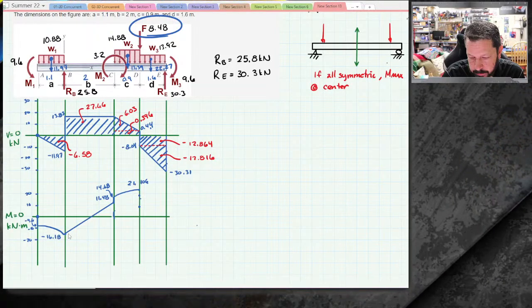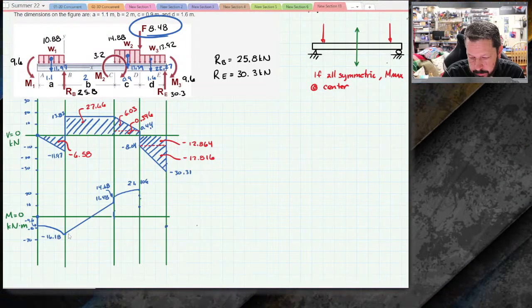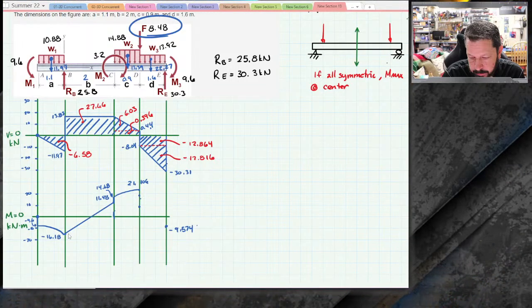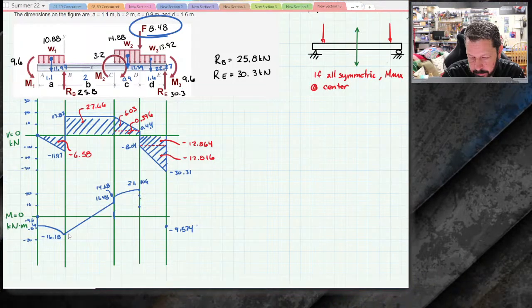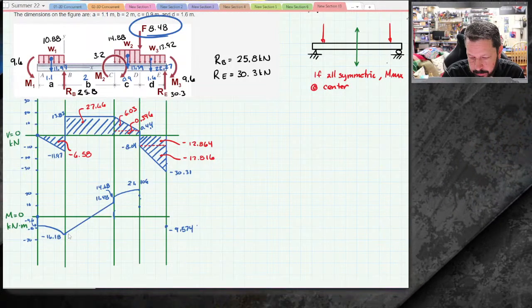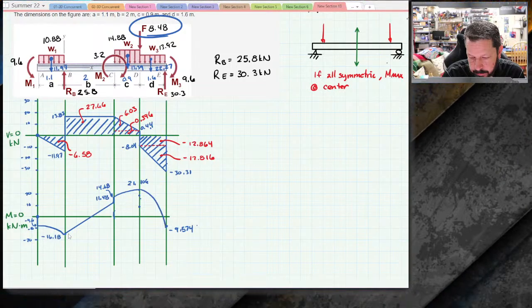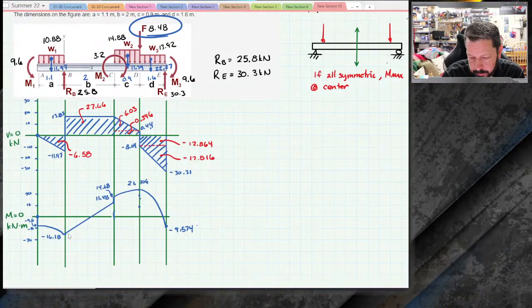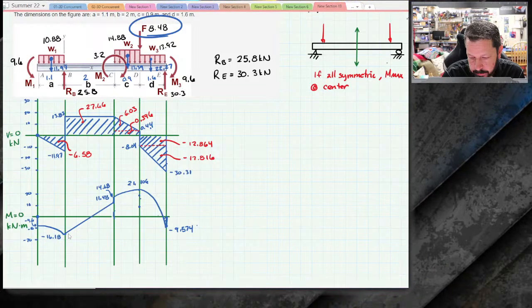Okay, so this one on the right hand side here, the total here will bring us from 21.106 down to negative 9.574. It crosses 0, and then it actually starts at negative 8. So it has a little bit of slope to it, but it gets more and more steep, so more and more negative. So it'll do something like this. And then M3 is 9.6. I'm at negative 9.57. I want to say that is rounding. So we got that one little weird blip at the end.